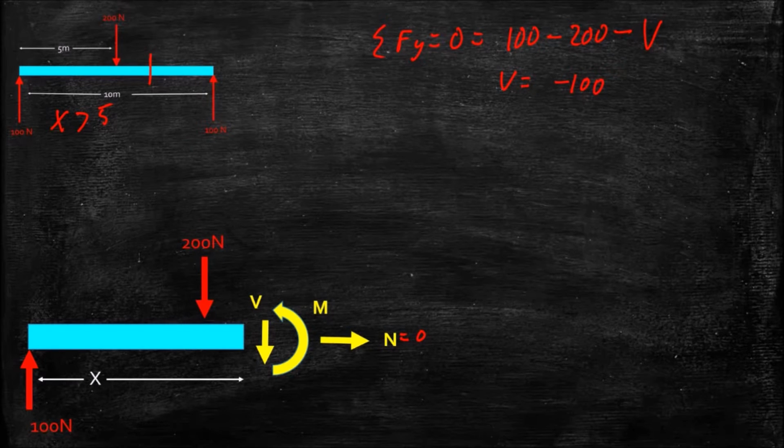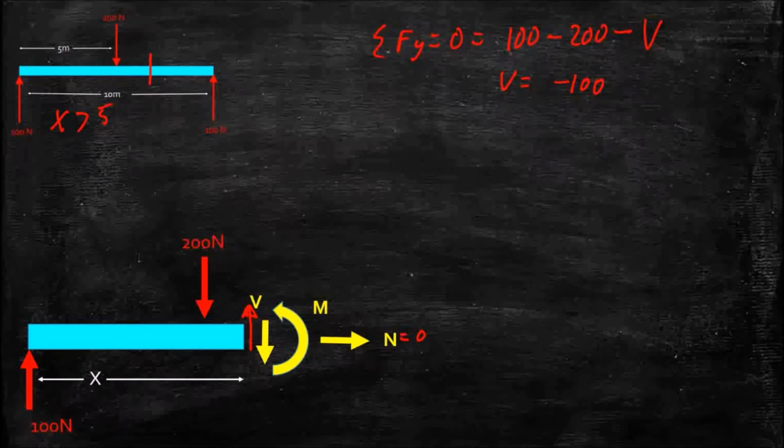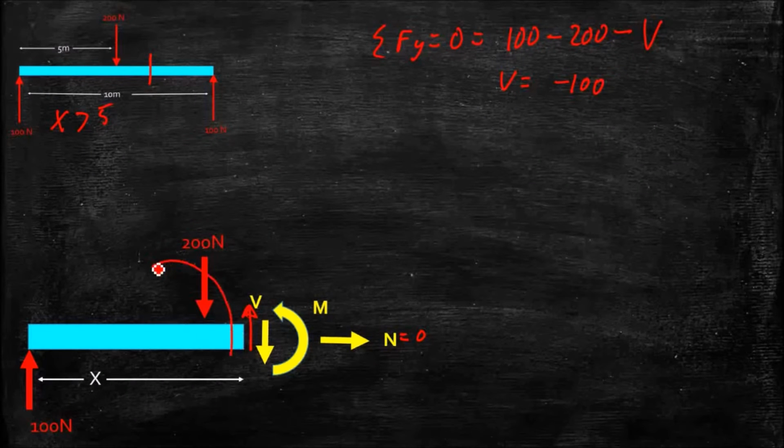Now I drew the arrow in the positive sense for our shear by our sign convention. And we got a negative value for V, so the actual force must be pointing upwards. An upwards pointing force there will result in a counterclockwise rotation. So that is indeed a negative shear force, because it gives us that counterclockwise rotation according to our sign convention.